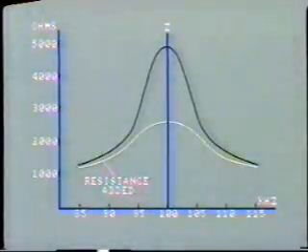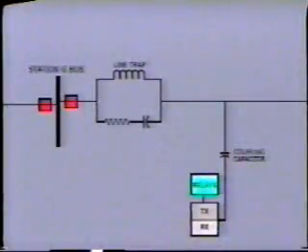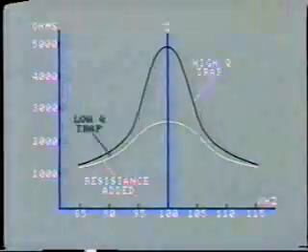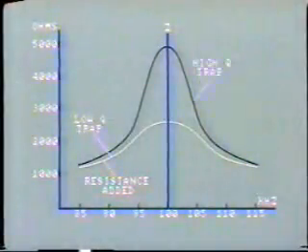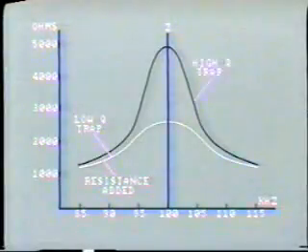a resistive characteristic. The resistance is usually connected in the capacitive branch of the line trap, and its value is chosen to match the line characteristic impedance, say 400 ohms. This type of line trap is known as low Q. The high Q wave trap has lower resistance and therefore relatively higher quadrature or reactive component.